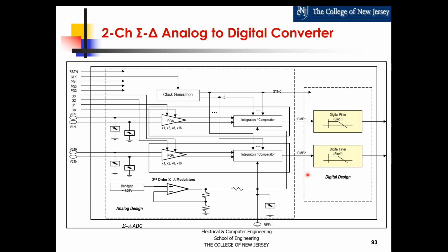In the limit, that function has a value of 1 at 0, or DC, in the frequency domain, and then that sinusoidal response in the frequency domain dies out in a 1 over x fashion, and it gets to 0 at infinity in the limit.